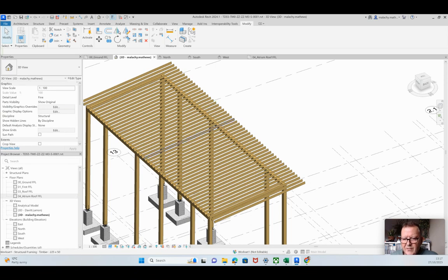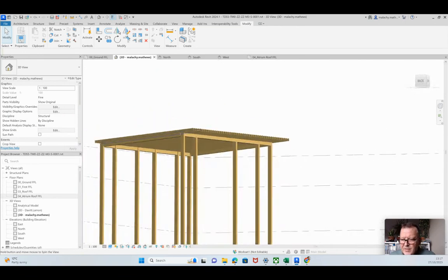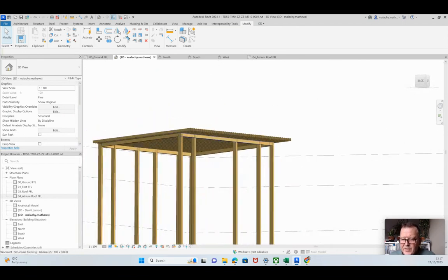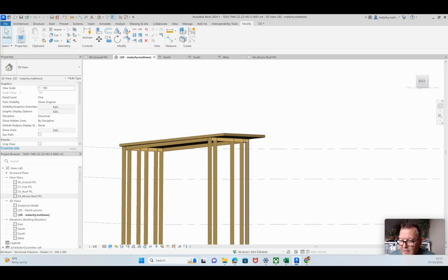I'll create a fascia around that as well, and then the walls for the interior side, if you like, will come up to the underside of this beam here. So I'll have to create a fascia in underneath any of the exposed bits there. If you remember, we've got windows running across here as well. So again, I might run something like a curtain walling system on the front of those beams, of those columns there. So something like that.